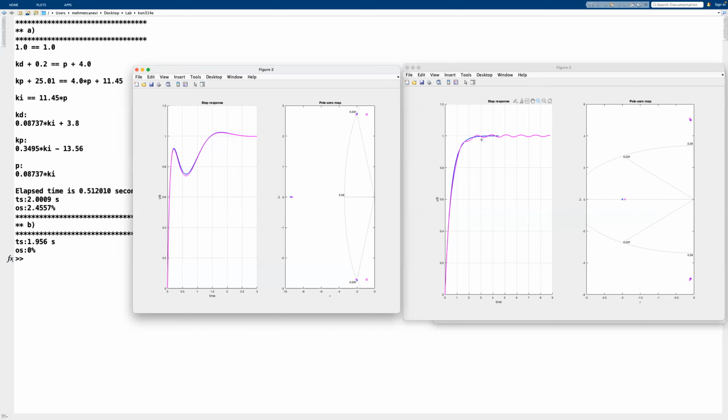Therefore, what the optimal solution seems to be in this case is to use a notch filter, where the notch filter tries to band stop the frequencies of the open loop system. And well, we are trying to then add some poles and zeros so that we get our wished behavior.